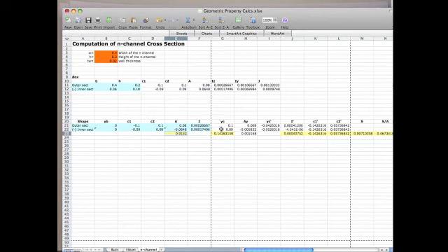And when it gets the weighted area multiplied by the moment, the first moment, I get a negative value here. All right? And it compensates everything correctly. So the negative areas work fine. Just make sure you put a negative sign in front of the area.